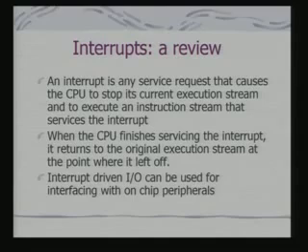The CPU stops its current execution and starts execution from a different instruction stream which is targeted for handling the interrupt. And when the CPU finishes the interrupt, the execution returns to the original program. We shall see how this mechanism is really implemented in PIC.